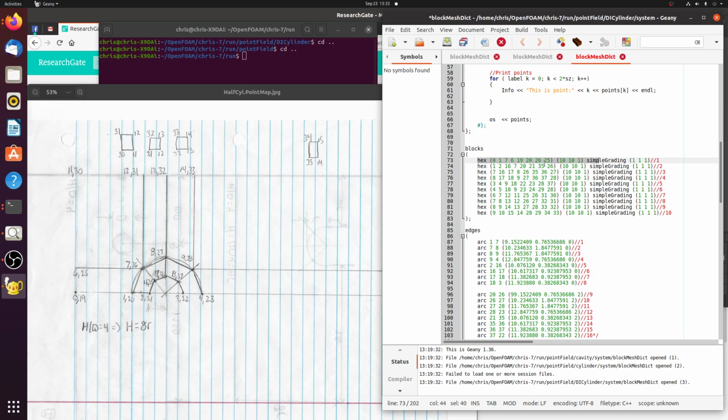And we just did a meshing of 10, 10, and 1 for all these, just to show that when we're finished meshing, the lines are supposed to match up. I'm not an expert on meshing, but I'm learning a little more that I'll mention in this tutorial as well. And about when we go from a fine mesh to a large mesh, the maximum size is 20% larger than the fine mesh for the coarse mesh. And so anyway, that's how you specify blocks.